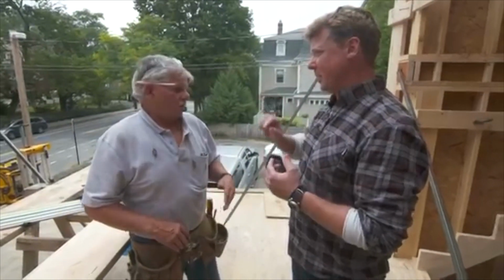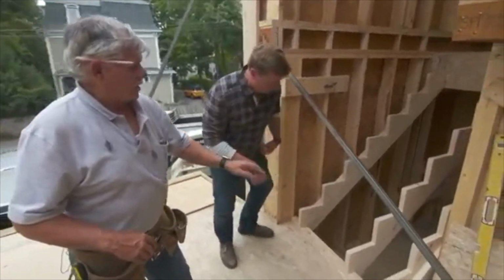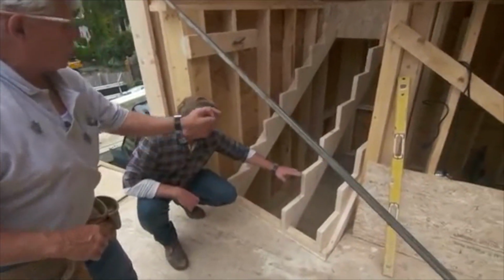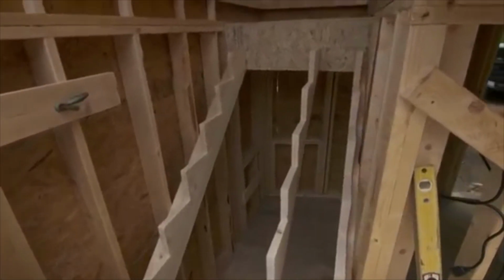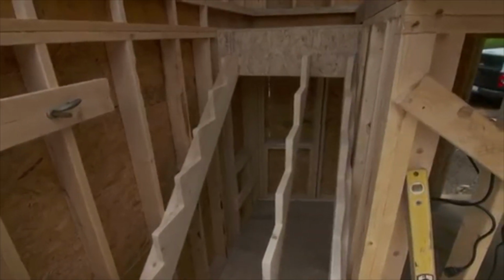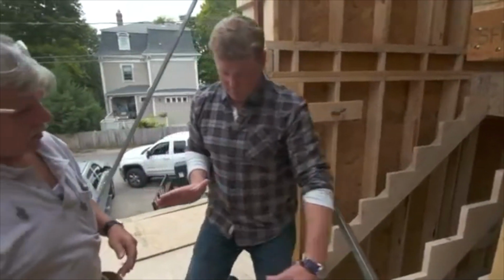They can vary a little bit, but you take one run of stairs right here. If the riser height changes, and not each one, but a total of 3/8 of an inch or more, technically that stairway is illegal. So we need a level of precision and comfort in terms of the height, and then the step itself, the tread where we put our foot.